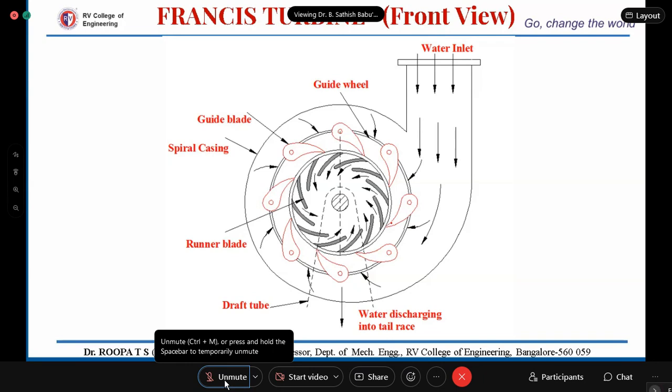It's a reaction, axial flow and medium head. Pavan, two classifications are correct. Why did you go wrong in one? Anyone else? Is it radial? Ma'am, it is a radial flow turbine. Yes. So the Francis turbine is a reaction turbine wherein we can see radial flow and medium head.